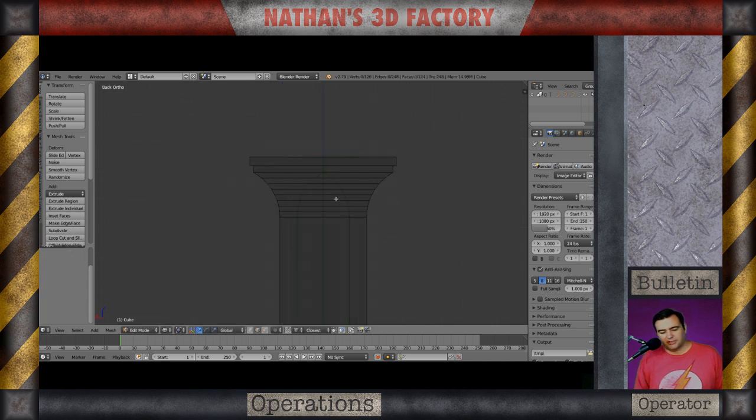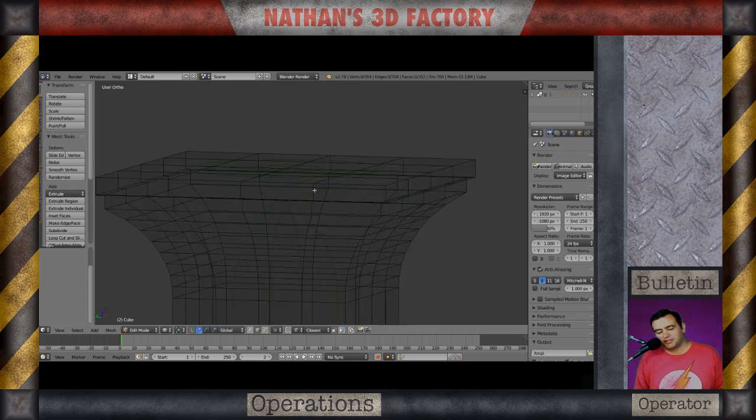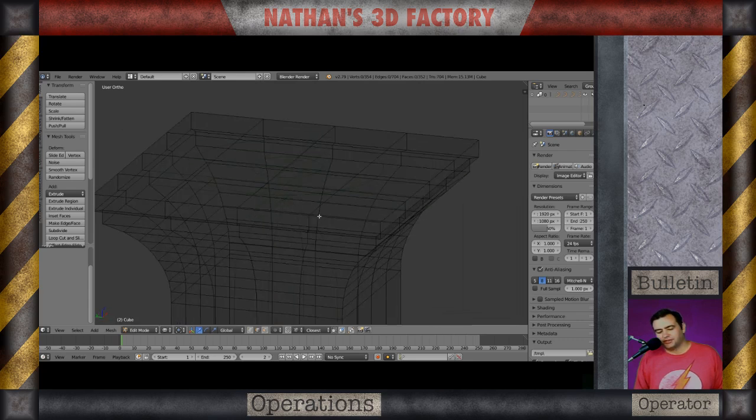So now what I'm doing is I am adding some loop cuts so that now there's something down the middle of the object. There we go. Now I'm just going around and looking at that. And I'm going to create these other loop cuts. And I'm going to be working on these loop cuts to where I'm going to be adding in kind of the arch element here. So I'm going to be doing some merging to make sure that these are correct.